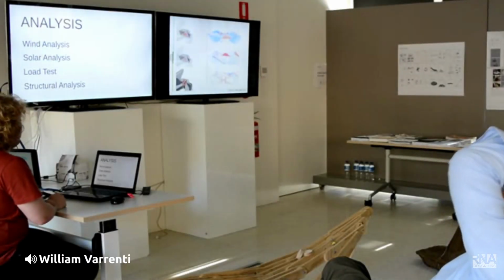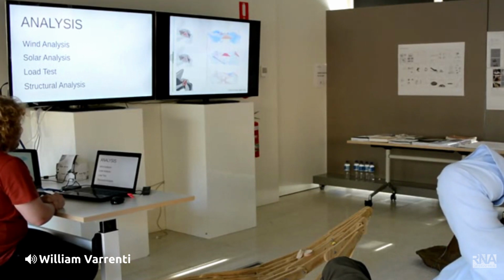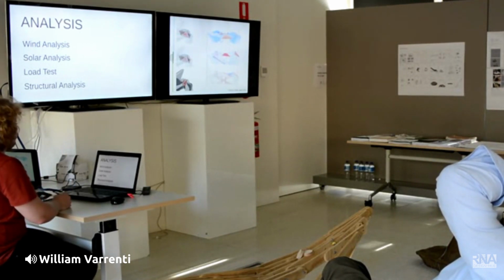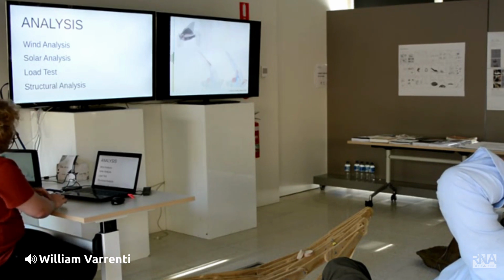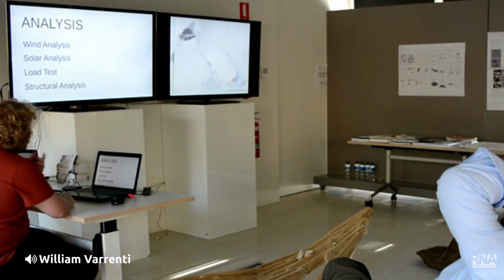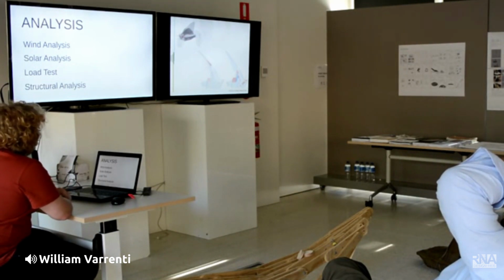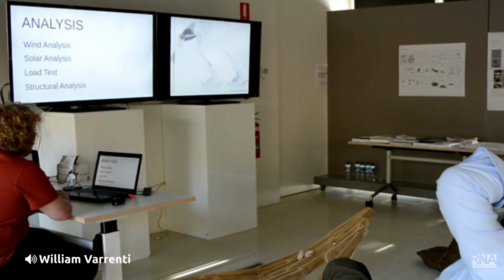Some cross-bracing. The middle section with exaggerated deformation, you can see that it would sag. So we initially introduced additional members and then determined that we needed extra vertical members to keep it static. And then we looked at the local forces and ensured that any areas that were under large amounts of stress were in compression as to fit the material, and looking at where to introduce the additional bracing.